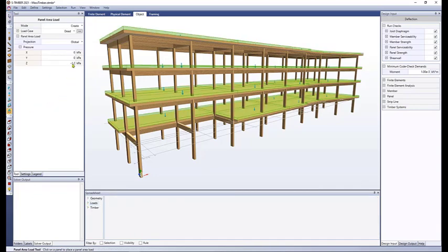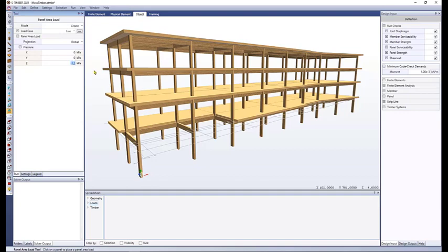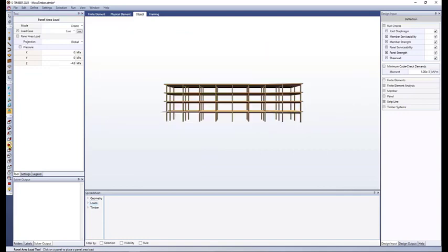Let's now define the live load. In the same way, I will assign minus 4.8, and for this I will select the front view to assign it to the first 3 levels of my structure by using the mouse. Then I can assign a roof dead load for this same load case, and this will be more or less about minus 1.9 just for the roof.